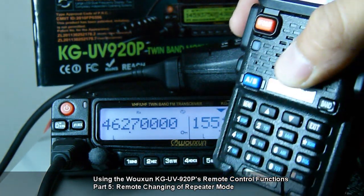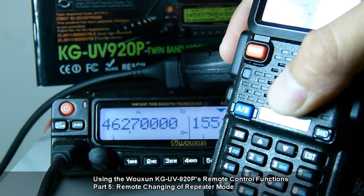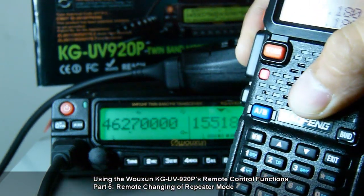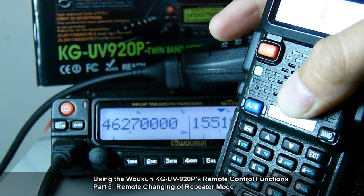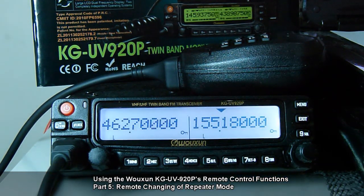There's that beep, and then within 30 seconds you do procedure 3C. So hold the PTT, key in 0, 3, and the matching mode code for radio mode is 1, and release the PTT. This time the KG-UV920P would reboot into normal transceiver communication mode.